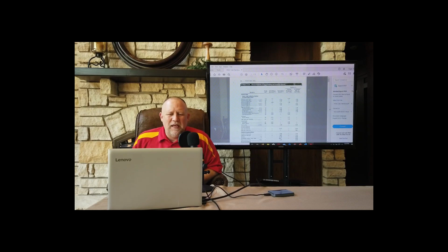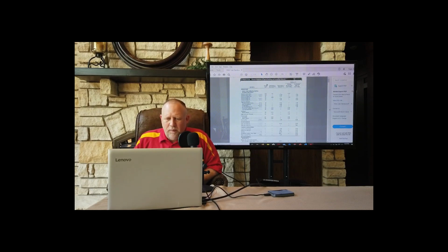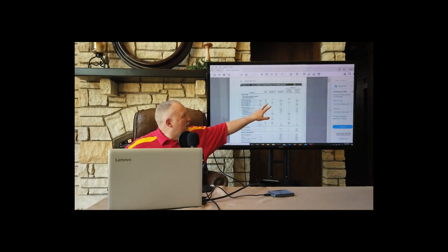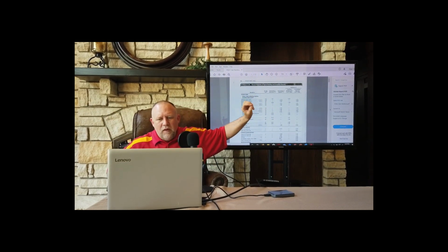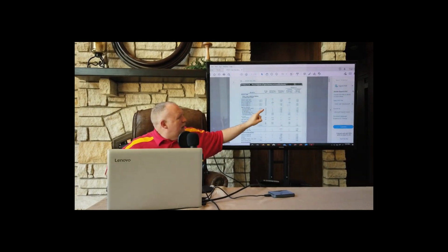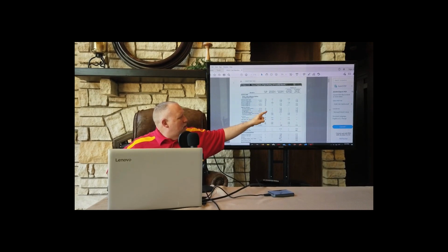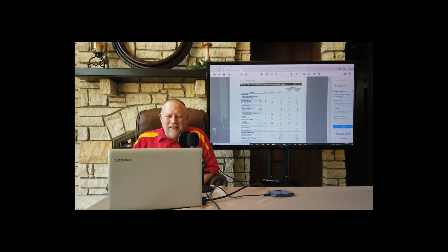The first thing that we need is to get the thermal properties of some typical building insulating materials. Right, so there's the description on the left, the density in pounds per cubic foot. That's not that important in this class. And then the important part is the last 2 columns, the resistance to heat transfer, the R value. Either it is going to be listed in thickness per inch, that's the second column from the right, or for the thickness listed, that's the very far right column.